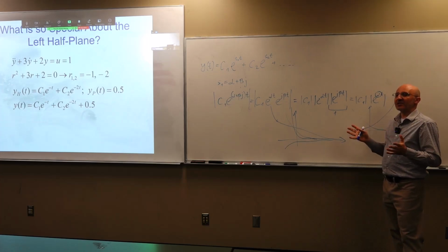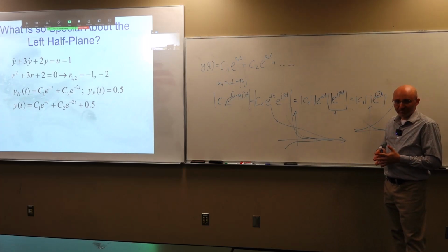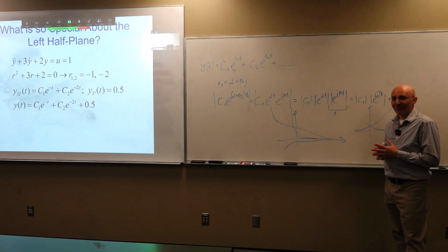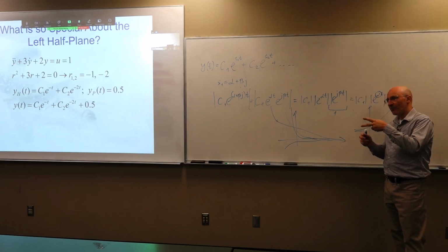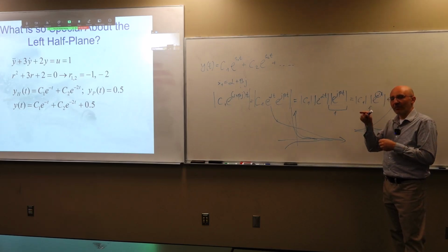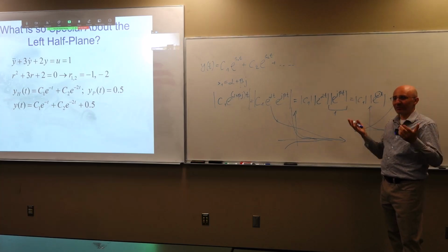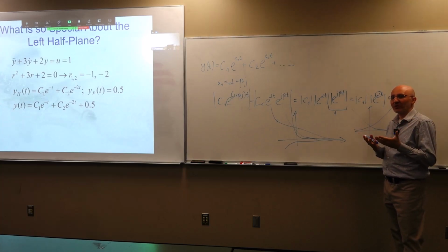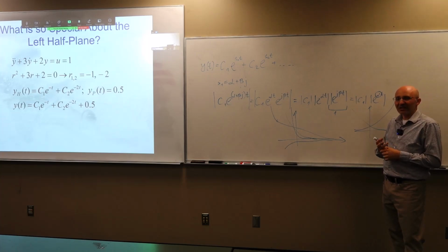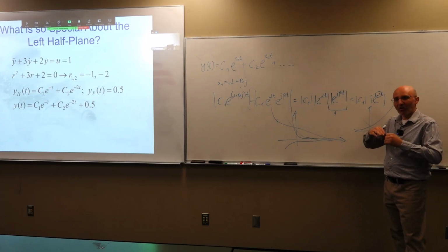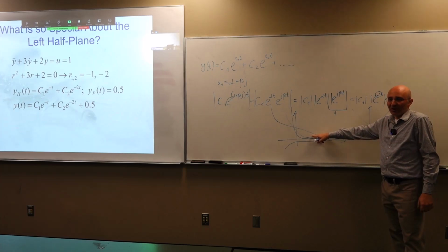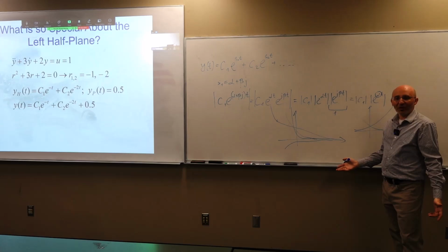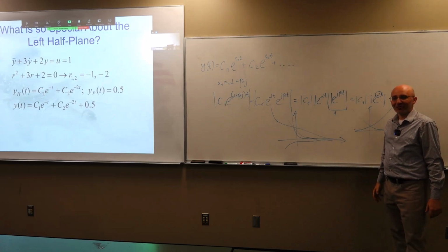And this is what brings us to the theory of dominant poles, which you hopefully also heard about in Controls 1 theory, in the first course on classical controls, where we're using the rightmost 2 poles or single pole as dominant poles, most important poles, which are imposing how system will converge, how fast it will converge, settling time and all of these things, right? How fast it will settle. Because the slowest one in the sum will be dominant one. It will tell you how fast you can converge.